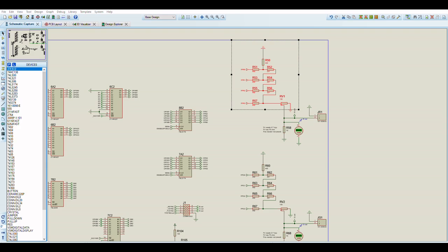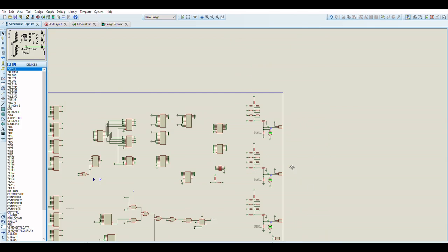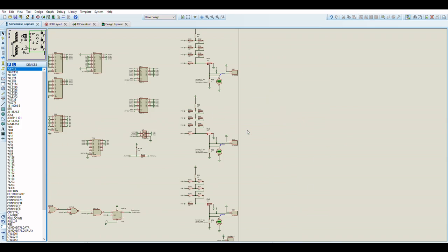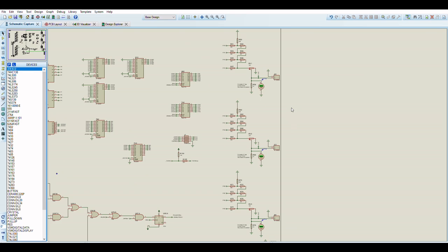This section of the board uses an updated resistor ladder arrangement compared to the original board. I redesigned this to output more SCART-like levels. I wanted to make the output definition a little bit more accurate, so I added the ability to tweak the output here with variable resistors.